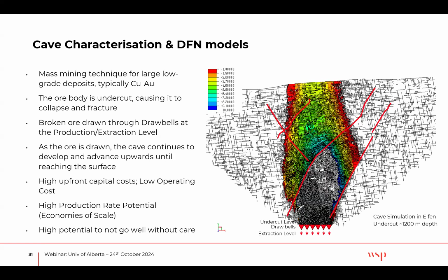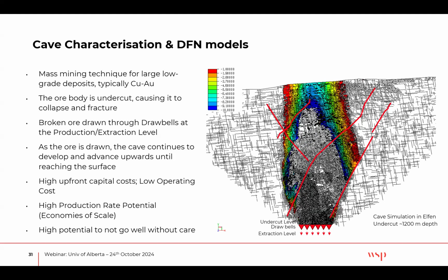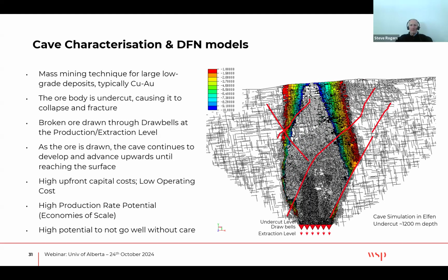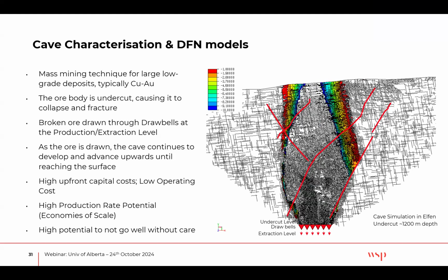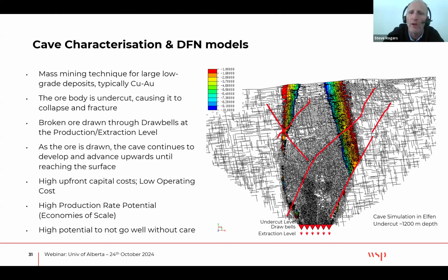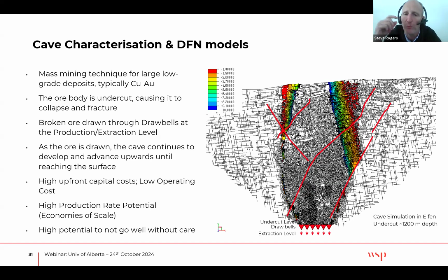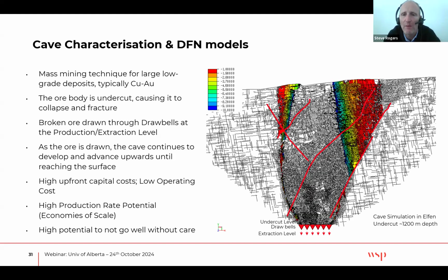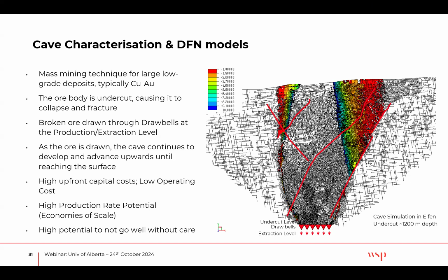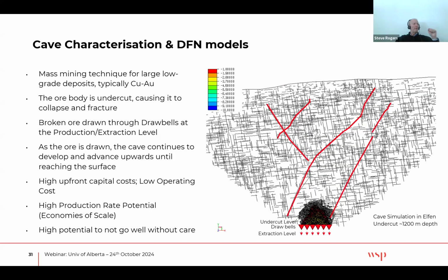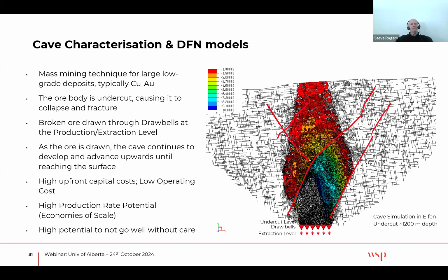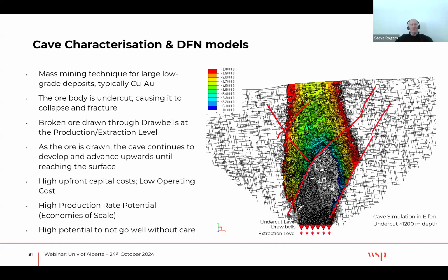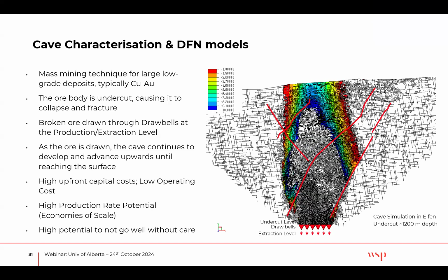Okay, so you probably have that cohesive element in the mesh, right? Yeah. And actually, the mesh opens or creates a fracture. So you can see, when it starts up, the part that's flowing now is all broken material, but that's come because the mesh itself has broken down. I don't think it will split below the smallest element, but it will break elements. So it's conceptually similar to UDEC and its Voronoi sort of mesh, although it's a little bit more efficient than that.